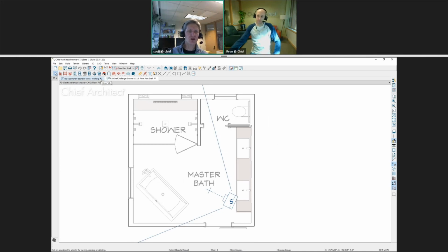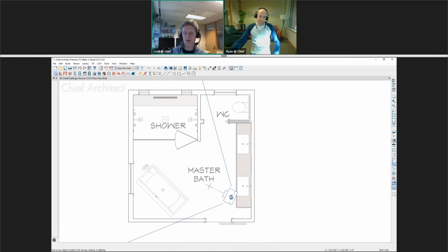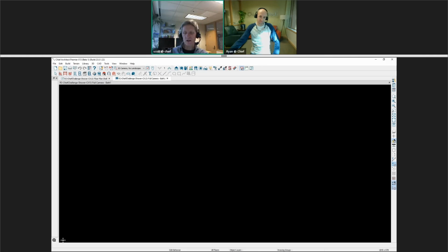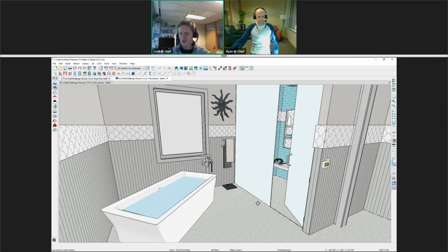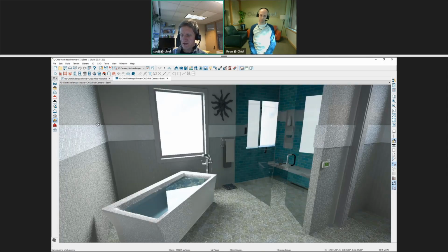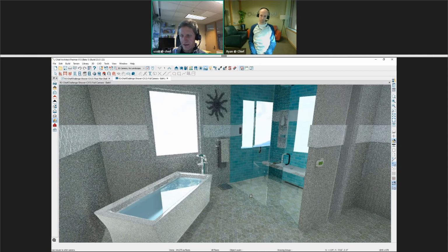So, without looking at your plan, let me just grab this particular shower that I have here that has a glass wall in there. Let's turn on the vector camera. That'll make it pretty easy to see exactly where we have that. So you're saying that the camera is going down below where my cursor is into the floor? Yeah, see how you can see that line there, and you see the subfloor through it when you go into your rendering. Let's switch this over to the physically based. And if I zoom in a little bit, it's not showing on that.